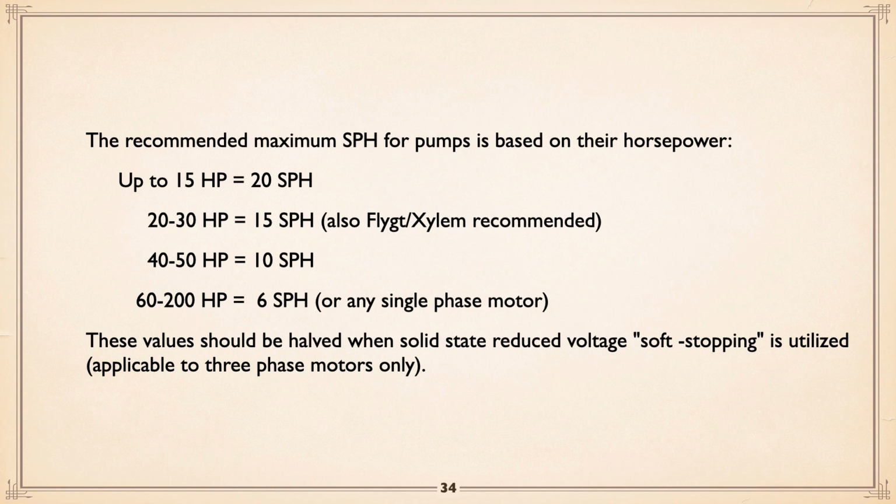These values should be halved if you're using solid state reduced voltage soft stopping, which we get into in electrical, because it's only used with three-phase motors. You are playing with that motor operating at reduced voltage for a period of time. So it's hard on the motor. You want to halve these numbers if you're using a solid state reduced voltage starter.